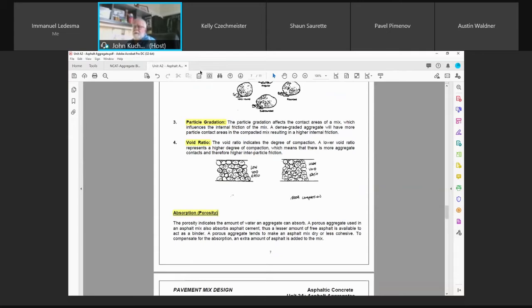And also, as far as water, if you have aggregates that absorb a lot of water and your stockpiles and your bins are wet and you're batching asphalt, it's got to be that much longer in the dryer, in the kiln, as you're drying your aggregates. Because of our reduced content, we're not looking at the batch plant operation, which I typically do. We look at the batch plant, we look at the various aspects of batching, the sequence of batching. But anyways, aggregates are just thrown into a big, circular, long kiln that rotates. And there's a flame in there and it heats those aggregates.